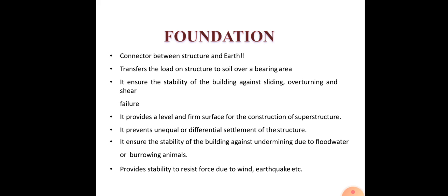Then it prevents the unequal settlement of the structure. Due to the load, there may be settlement of structure at times. So it is the foundation which prevents the unequal or the differential settlement of a structure. Then it gives stability to the building against any forces of wind or other forces which can lead to overturning. Then it ensures the stability of the building against say flood water.